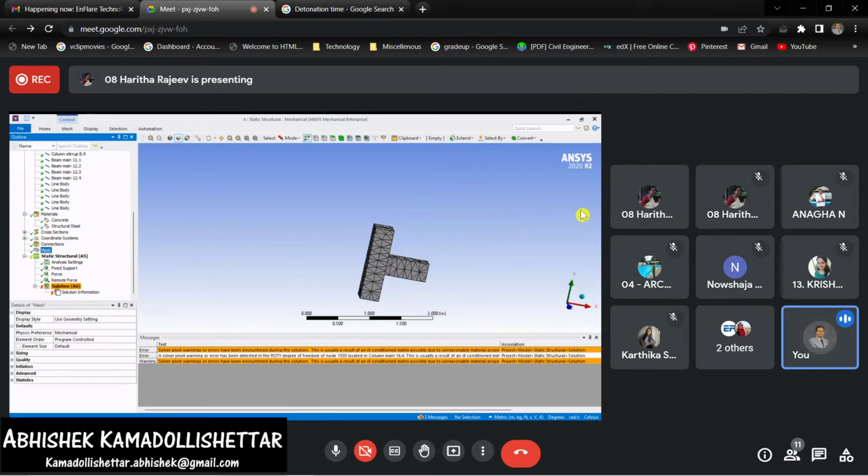What is the size of the geometry you have taken? Sir, the column is 1.2 meter height and the beam is 6.67 meter projection. Then no problem. In the mesh size, make it 50 mm.